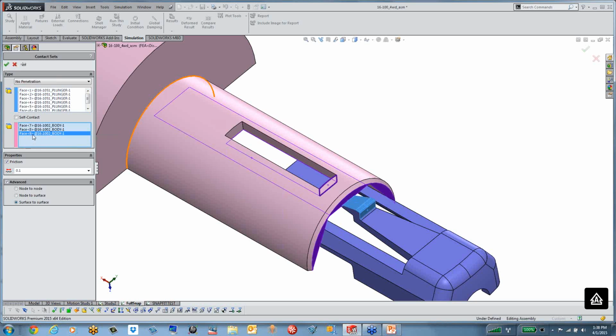If the material is softer, then you select the faces or the geometry corresponding to the softer material on the top, and if the material is stiffer, then you select the geometry on that material in the bottom selection. Okay, so hopefully that is clear, because a lot of times you might just define the contact, but if you select the softer material in the bottom, it can actually lead to any divergence issues.